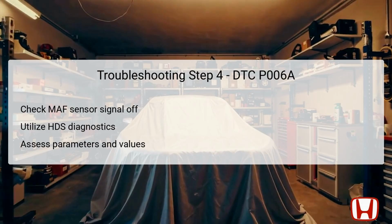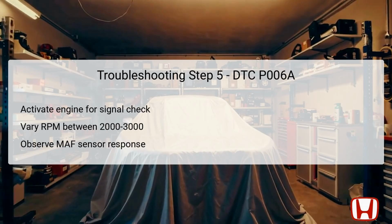If the current conditions match this threshold, you can move on to the next step. However, if there's a discrepancy, it may indicate a faulty MAF or intake air temperature (IAT) sensor 1, necessitating their replacement. By utilizing the HDS, you ensure that you are collecting accurate data for your diagnostic efforts, aiding in effective troubleshooting.